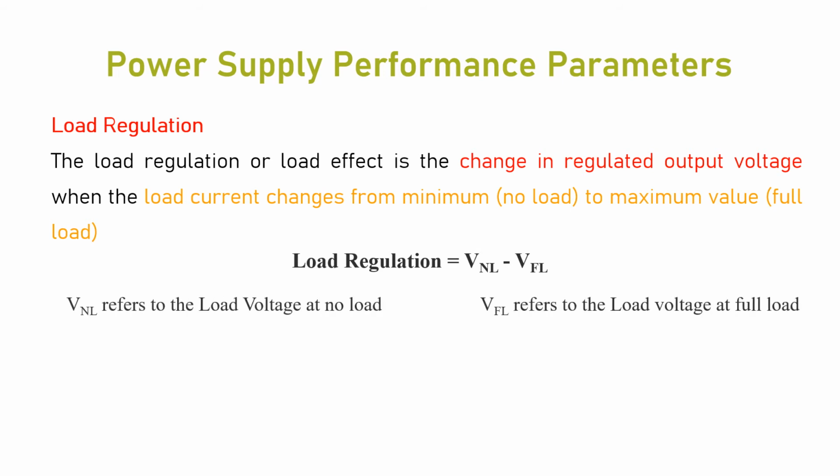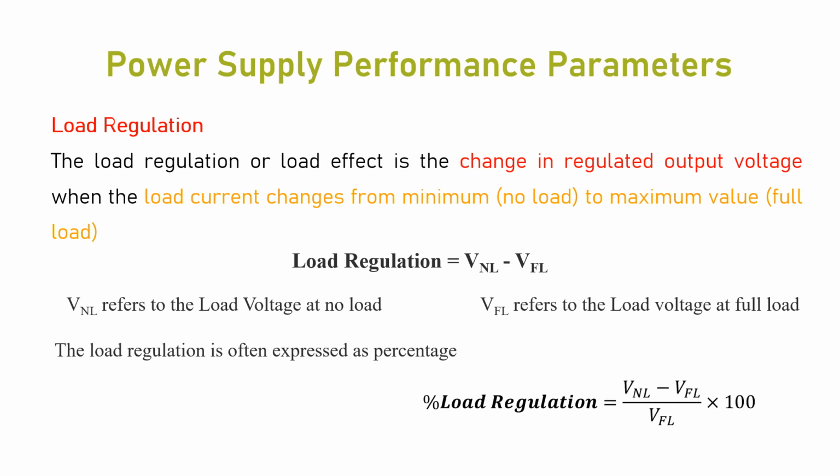There we are not going to connect any load to the supply. It is an open circuit we consider, and VFL refers to the load voltage at full load, where we connect a load across the supply. Also, the load regulation can be expressed as a percentage: percentage load regulation equals load regulation with respect to full load voltage, so (VNL minus VFL) divided by VFL times 100%. So this is about load regulation, the first important parameter of a power supply circuit.